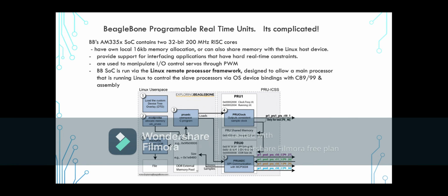So the SoC is run via the Linux remote processor framework, which is designed to allow a main processor that is running Linux to control a slave processor via operating system device binding using basic C and assembly.